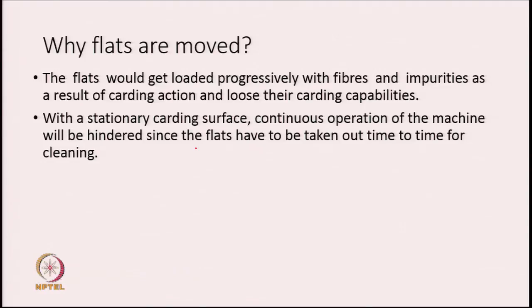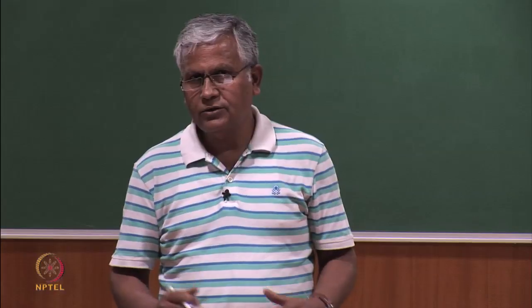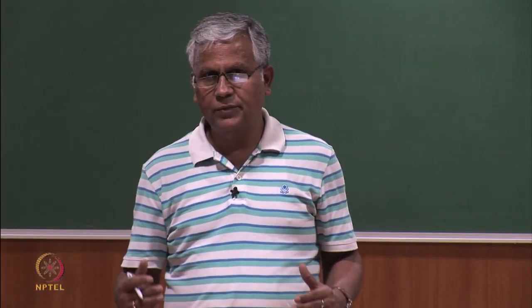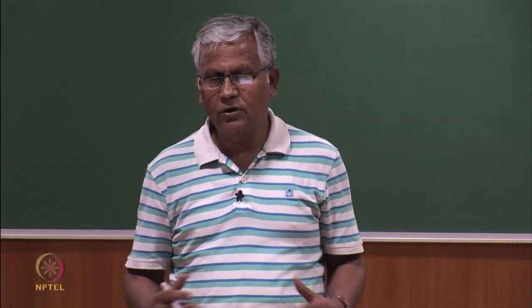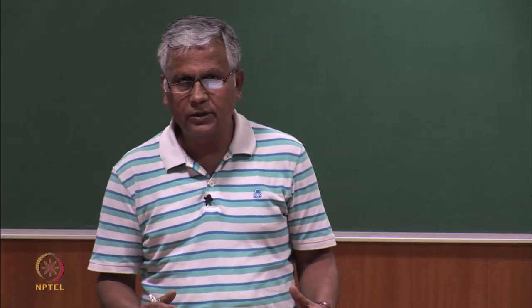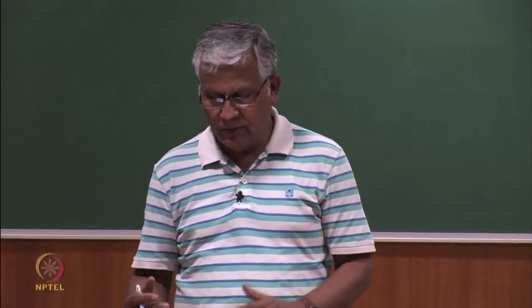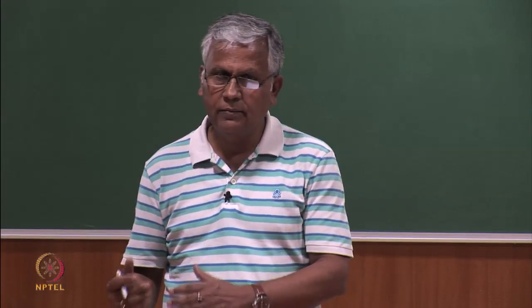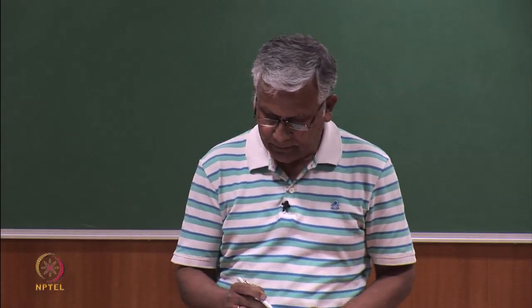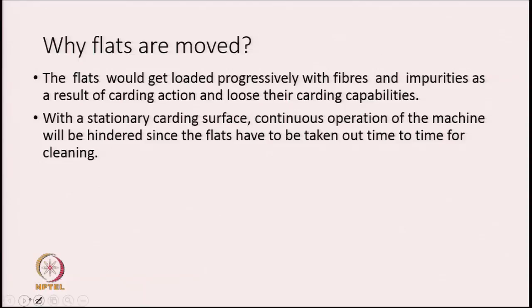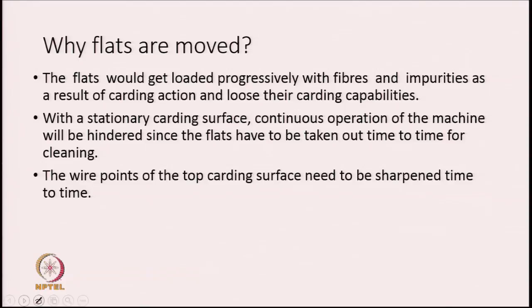That is, if I do not allow the flats to move, then once the flats get completely loaded with fibers or trash or impurities, you have to stop the machine, remove the flats, clean them and put them back. So, this is the problem with stationary flats.